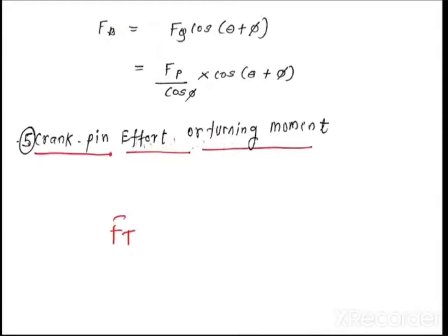This cramping effort, tell me until it is produced. A cramping effort, your turning movement. Cramping effort means what? Torque. Note this. Effort means torque. Take a small gear, take a large gear. When the smaller gear is rotating the larger gear, it requires a larger effort. When the larger gear is rotating a smaller gear, it requires a smaller effort. So torque is nothing but a turning effort.